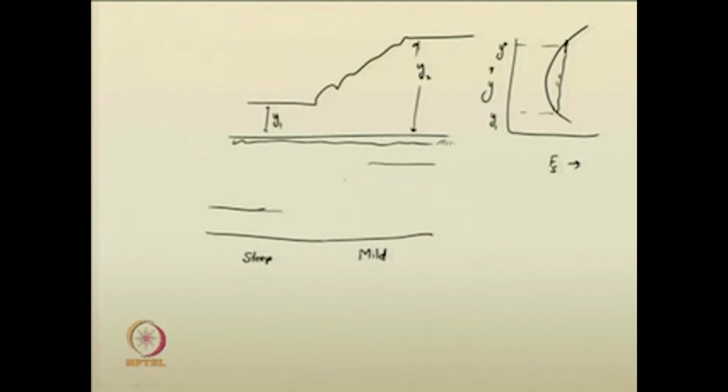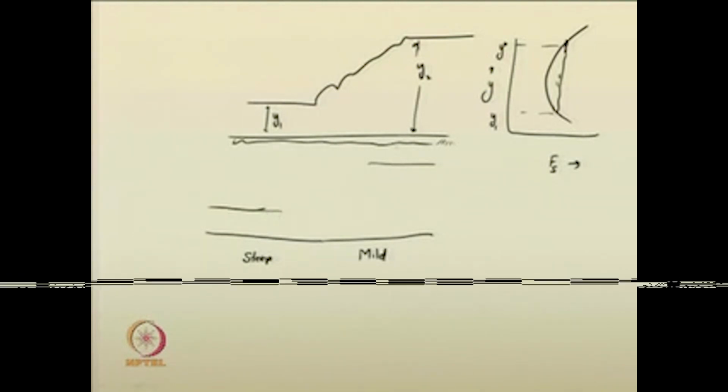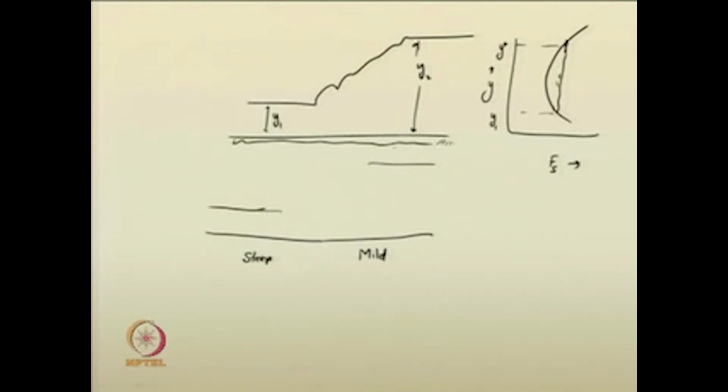There will naturally be some hydraulic jump when the change is from steep to mild, that is, from supercritical to subcritical flow. How will you incorporate the jump? Whether the jump will be on the steep slope channel, in the mild slope channel, or somewhere else. This is the question I would like to raise.